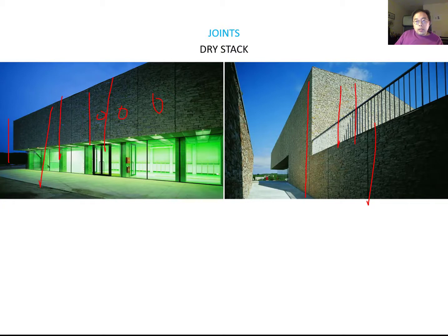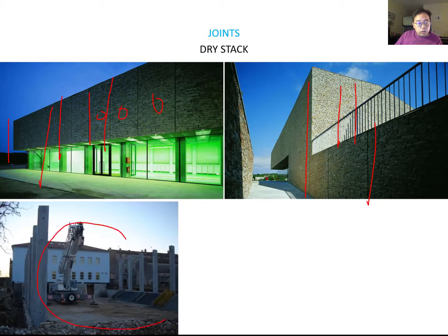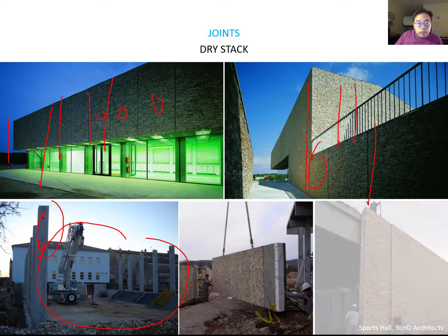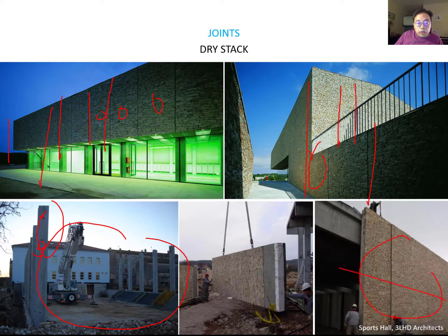Then this panelized wall assembly is hung over the concrete beam and slab. You can see the structure, and you can also see the clip here. With this panelizing system, the hanging is done using a crane, and it is easy to hang the panels over these clips, making a continuous wall. Each panel has this expansion joint or a tight joint inside, which makes it easy to protect against water.